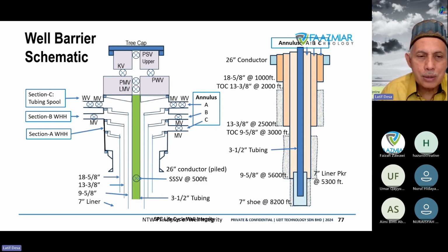After 1 week, 1 month, or 1 year, we can see the pattern. If the pressure starts to show some indication of extreme, then you have to think about all this annulus pressure having to be managed properly by a bleed-off system or by doing some repair on the annulus that is causing the leak of hydrocarbon to the annulus. Okay, this is the schematic of the drawing.